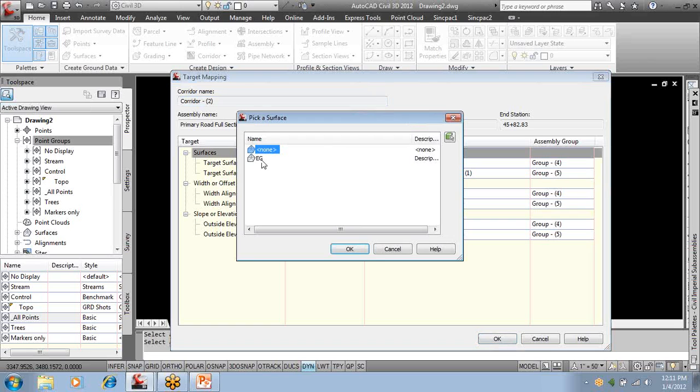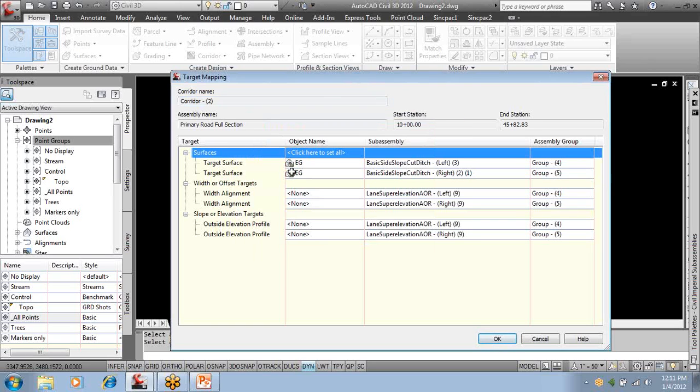At this point, we're going to keep it simple. I want it to daylight to existing ground. I can also transition. So if I have lane left and lane right, I simply tell it to follow this alignment or go out 12 feet. It'll automatically follow that lane. You can use the intersection wizard to put that left turn lane in. We have offset alignments that we can build, and it will either follow the grade or the profile design if I assign it here.